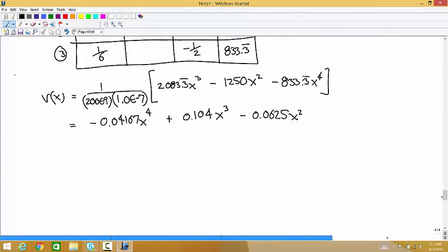Okay, so how do we find the minimum value of the deflection? Put in 0 for x. Yeah, take the derivative and put in 0. Derivative, yep, right. So we want to minimize v of x. So we're going to set dv/dx equal to 0.